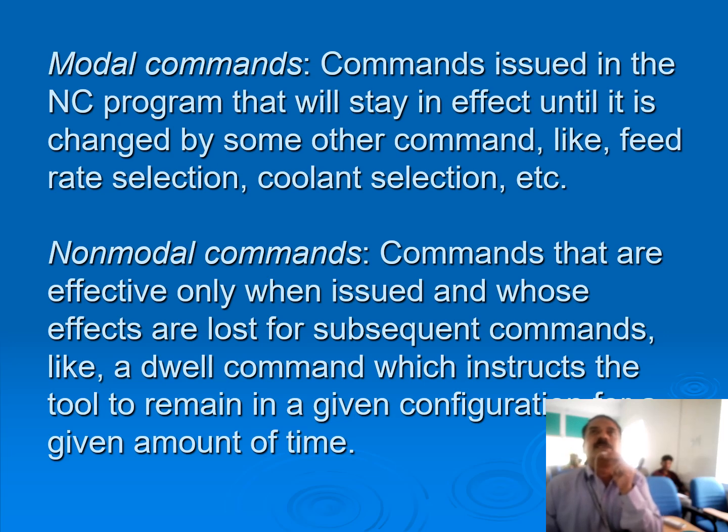Modal commands: commands issued in the NC program that will stay in effect until changed by some other command, like feed rate, speed selection, coolant selection, etc. That is modal commands. Non-modal commands: commands that are effective only when issued and whose effects are lost for subsequent commands, like a dwell command, which instructs the tool to remain in a given configuration for a given amount of time.